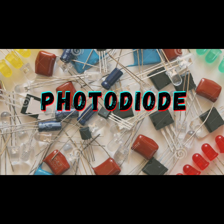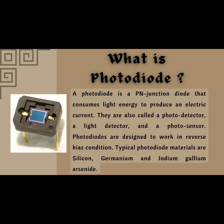Okay, today I want to present a photodiode. What is a photodiode? A photodiode is a PN junction diode that consumes light energy to produce an electric current. They are also called a photodetector, a light detector, and a photosensor. Photodiodes are designed to work in a reverse bias condition. Typical photodiode materials are silicon, germanium, and indium gallium arsenide.